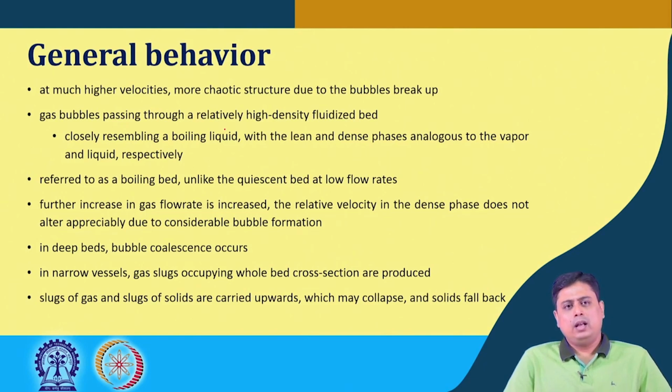Okay. In deep beds, that means when the fluidization bed depth is quite sufficient or higher, bubble coalescence also occurs. And in the case of a narrow vessel or shallow bed, gas slugs that occupy the whole cross section of the bed form, and such formations are frequent in a narrow vessel or shallow bed.